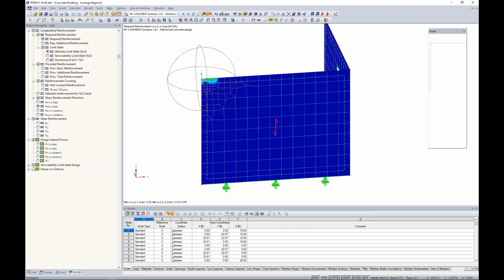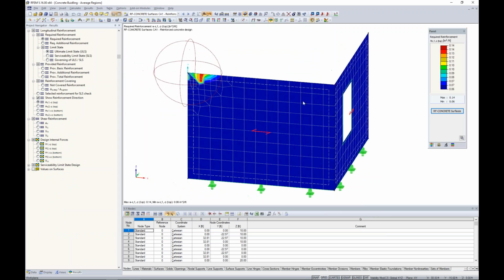Now, lastly, we can view this information graphically again, and we can take a look at the required reinforcement in the different directions. By all means, we still have these areas which have higher internal forces, which is fine. This probably stems from our rib and our panels framing into it behind this particular wall. But we're not looking at 0.95 inches squared per foot. Again, we're looking at the max of 0.3 inches squared per foot. So that is much more realistic.